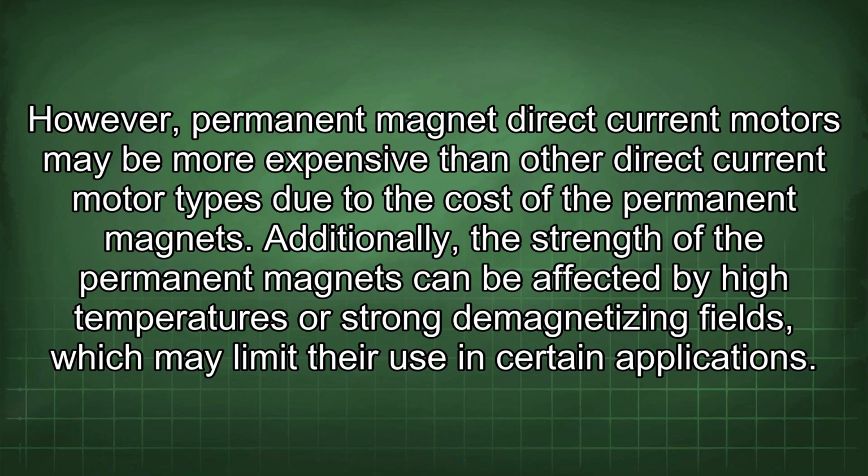However, permanent magnet direct current motors may be more expensive than other direct current motor types due to the cost of the permanent magnets. Additionally, the strength of the permanent magnets can be affected by high temperatures or strong demagnetizing fields, which may limit their use in certain applications.